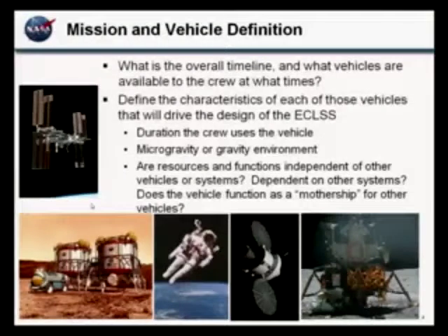You're going to need a lander and an ascent stage of some sort to get to and from the surface of the planet. And then you're going to want to do something when you get there, whether that's with rovers or with spacesuits. If you've gone to all the trouble of sending people, you want them to be able to explore and do the science and all that sort of stuff. So each of these pieces has a life support system, and they all are interconnected. So you have to think about all of them at the same time to some extent when working on your design.